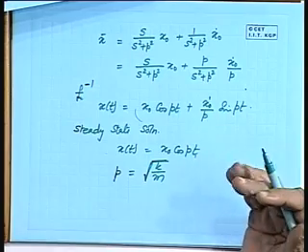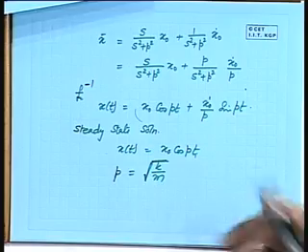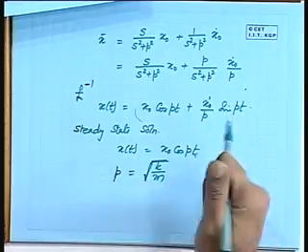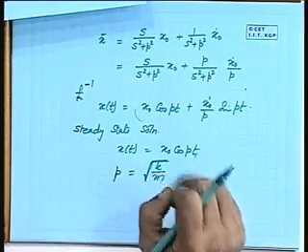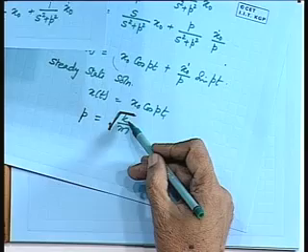If you make it heavier, then the frequency will come down. But it so happens that when you make it heavier, the strength also increases. So, it depends on how you disperse the material. Okay. How you place the material so that you can make use of this property. This is what normally we try to do. So, this gives us that type of a clue that the structural frequency will vary on the basis of K and M.